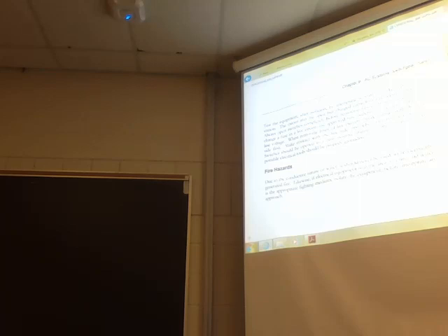don't. This is the part of this chapter that's very wrong. Never change a fuse in a live circuit. Just ignore that part. It should never happen.